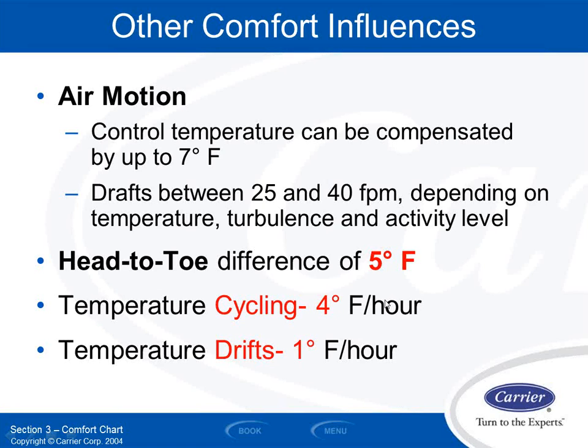Obviously, the better thing to do would be to heat from the floor, right, and return from the ceiling. But for cooling, it's better to cool from the ceiling and return at the floor. And nobody's going to put in a double duct system, one for wintertime and one for summertime. So they pretty much go with the dominant mode, which for most commercial buildings is cooling mode. Plus, a lot of the equipment is rooftop based, and it's shorter duct runs and easier to put ducting in a ceiling plenum than it is under the floor. So you tend to have a lot of overhead systems in a lot of commercial buildings. Just keep that delta T in check for the discharge air.